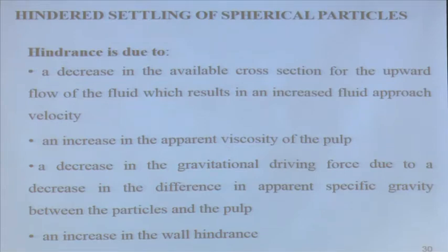So the resistance to flow will be more, which is nothing but the viscosity, but it depends on what type of particle you are feeding. If it is a coarse particle, the viscosity may not be affected. So for that I must have a viscosity model for non-Newtonian fluids. That is the problem we face when we deal with clays, like in iron ore processing and coal processing. The clays are very fine particles and they remain suspended. I introduce your viscosity problem into that.